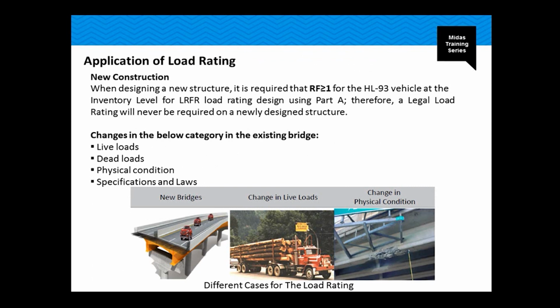In the application, when designing new structures, it is required that the rating factor is higher than 1 for the HL93 vehicle at the inventory level for LRFR load rating. Therefore, a legal load rating will be required on a newly designed structure. We're gonna define what the legal load rating is in the next slide.